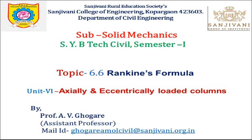So already you know how to determine the critical load on which the column will fail. That critical load is called the Euler's critical load, and symbolically it is represented by P suffix capital E. So that E is nothing but Euler's, right? So Euler's theory is also very important for the long column.